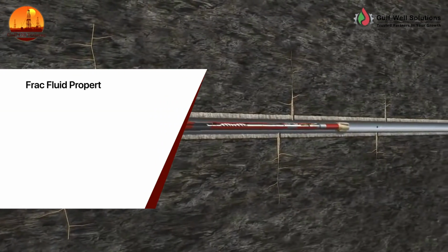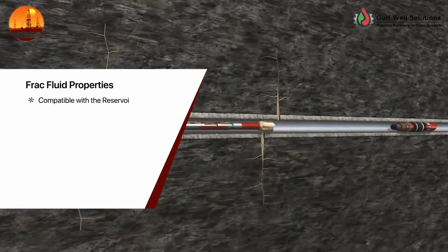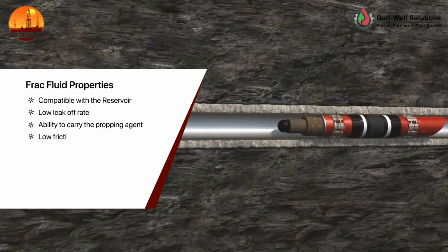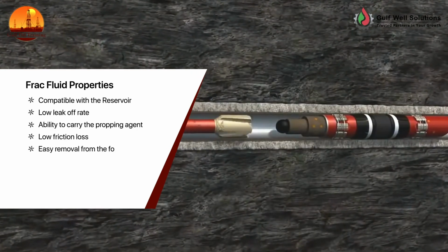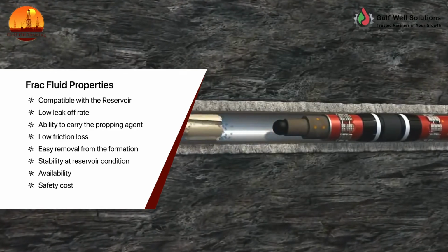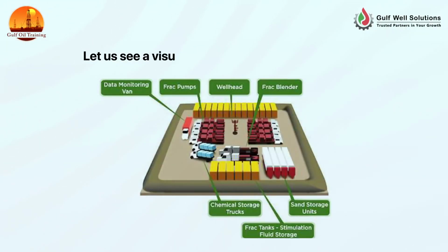Frac fluid properties: compatible with the reservoir, low leak-off rate, ability to carry the propping agent, low friction loss, easy removal from the formation, stability at reservoir conditions, availability, and safety and cost economics. Let us see a visual illustration of the frac job package setup.